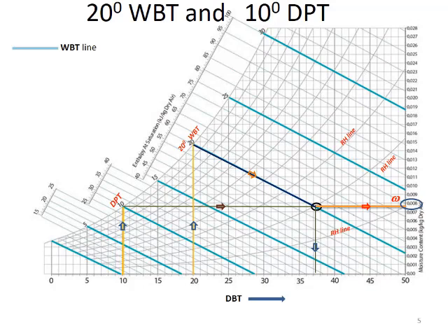The point is located, you want DBT, come down, so its value is around 37.2 degrees, okay, its temperature. Then for enthalpy, extend that WBT line, so it is intersecting at 57.5, and to know the RH, this time it is overlapping exactly with one of the RH lines, that is 20%, so RH at that point is 20%, that is the relative humidity.